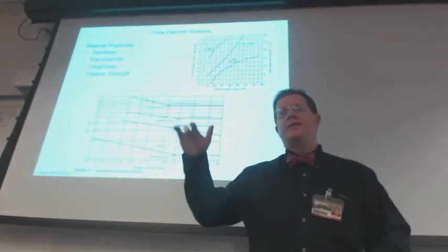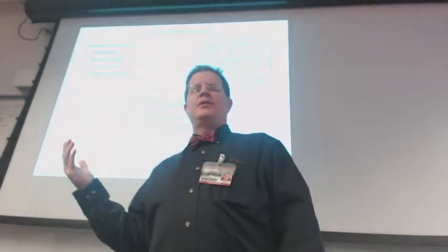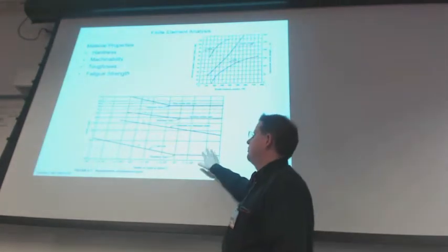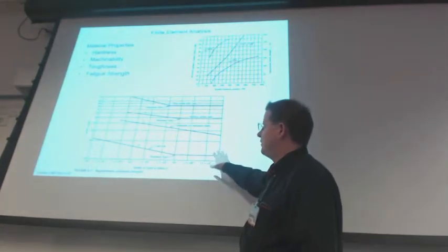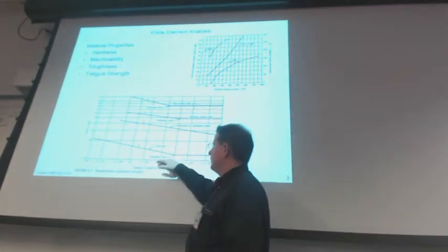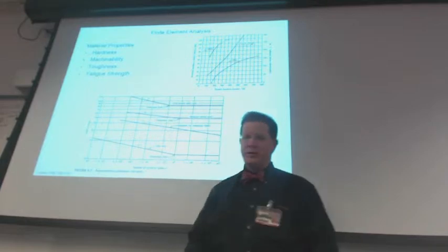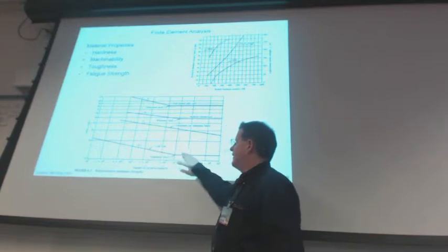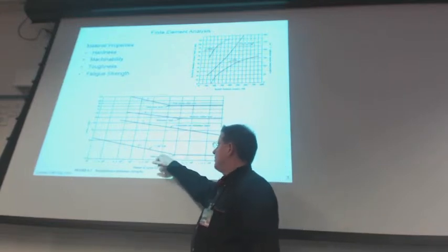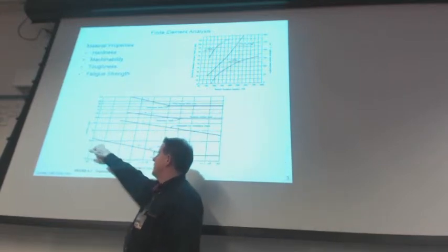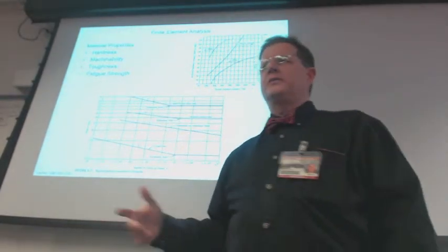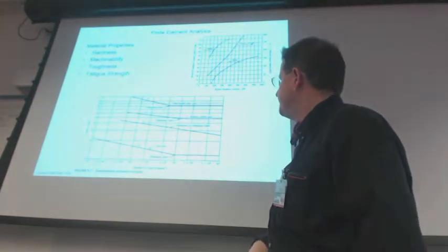Right, so if you have varying loads, this particular chart speaks to endurance strength. As long as your load is below the endurance line that they have here, or the number of cycles, if your load goes up and your cycle count goes down, as long as you stay below that, then your part's not going to fail.